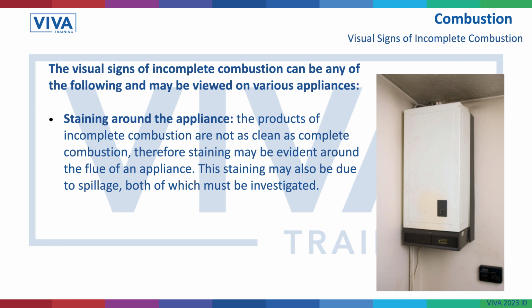I need to inspect it and check the seals on that appliance to make sure there are no products of combustion coming out. Make sure the appliance is burning correctly. Because it could be burning correctly, but if the case seal isn't correct, we could have some products of combustion. Instead of going through the flue, they could be released into the room or area where that appliance is located.